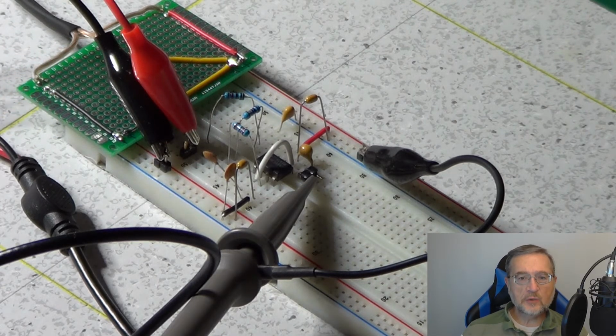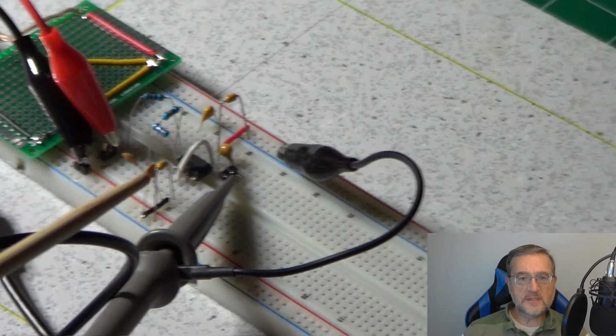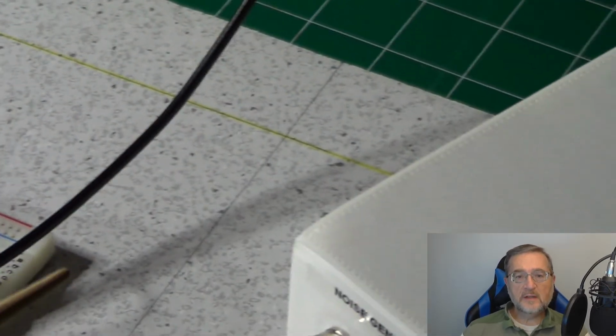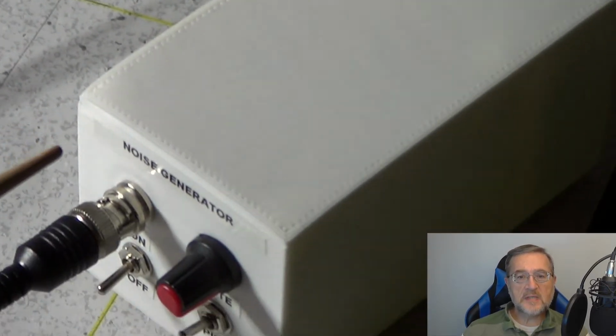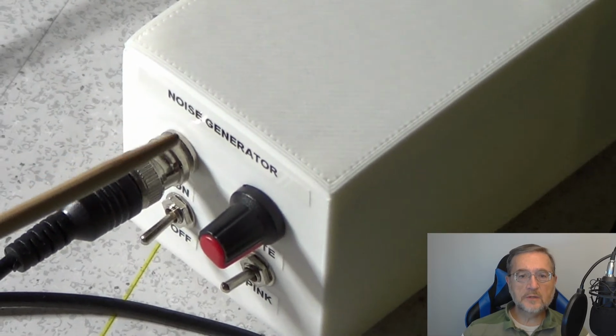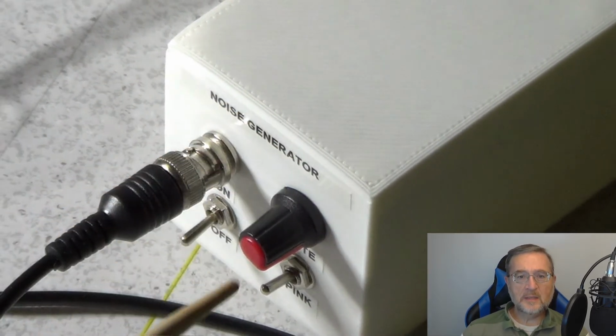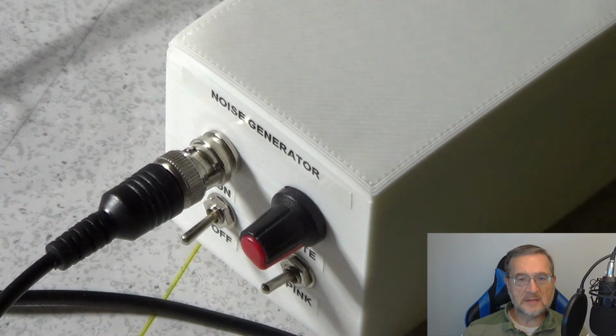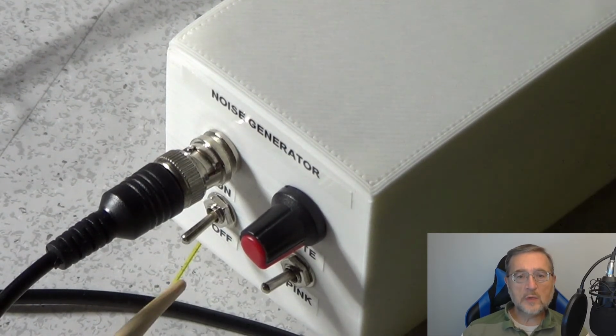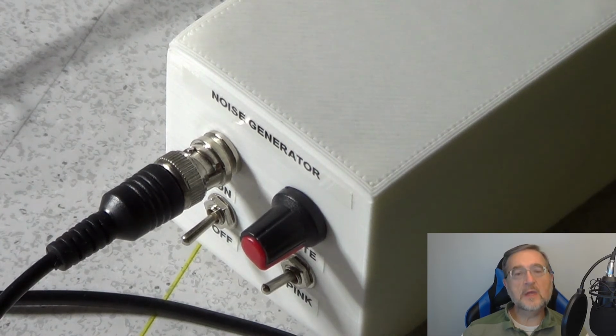The noise generator will provide a signal with frequencies spread all over the spectrum. The filter will take away all those frequencies higher than 5 kHz according to its response curve. Connecting the output to the oscilloscope, and in particular to its spectrum analyzer functionality, we will be able to visualize the response curve of the filter and see if it behaves like we expect.